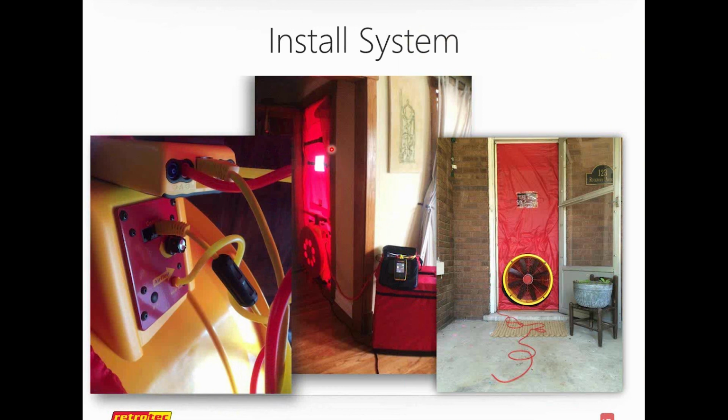However, you don't want to have it anywhere around here. You don't want your manometer, your gauge, in front of the flow of air, because that'll throw off your readings completely. If you can't avoid that for whatever reason, and I have been in situations where I actually had to put my gauge in the flow of air, you can add another tube to that and run it somewhere into the house where there isn't air flowing over it. Thank you, Mr. Wozniak. We will get to that.